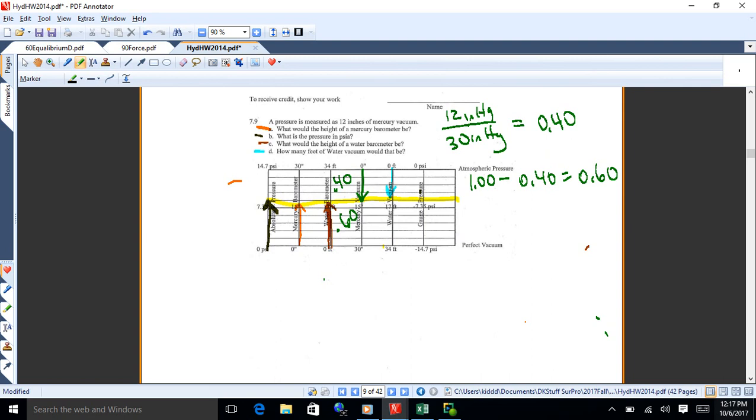Now, the two things to remember are that you always start at 0 and measure from 0 to the line, and then you convert the different units. That's basically what you're doing. So we've got 60% of the PSIA to go from 0 up to that line. The total is 14.7. If you take 60% of 14.7, you'll get the reading for the PSIA, which starts at 0 on the bottom and goes up. So that's 8.82.